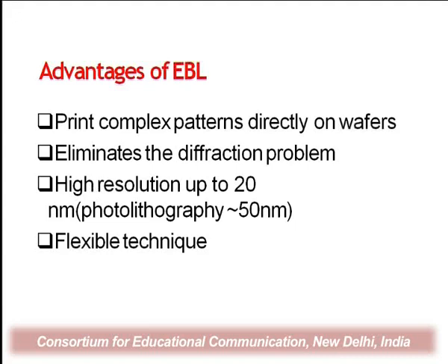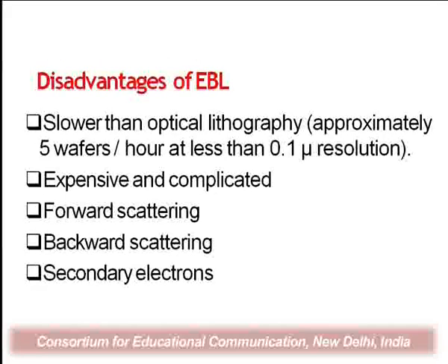Resolution up to 20 nanometers, which is much finer than the photolithography method, at 50 nanometers. This is the most flexible technique, and most devices are prepared using E-beam lithography. What are the disadvantages of electron beam lithography?